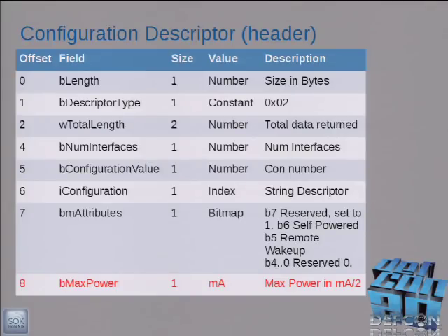Now, if you're going to make a little device, something kind of like this little preview, that is going to fake another device, obviously I have some electronics that are going to require a little bit of power of their own, in addition to whatever my thumb drive takes. Some people might be tempted to just crank up that power. Don't do that, all right? The problem with that is if you crank up the power and your port cannot provide that much power, it won't enumerate your device, all right? So usually 100 milliamps is pretty safe, and it's probably enough anyway, all right?